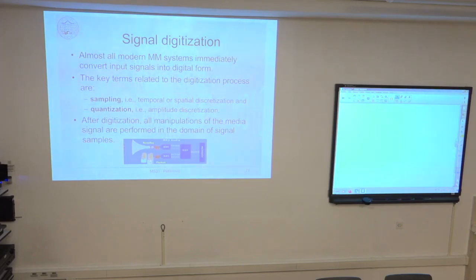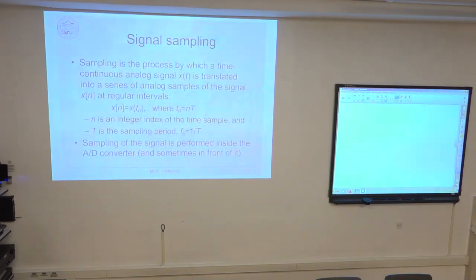For example, let's measure it with a multimeter, whatever, you have only a given number of digits to measure the voltage or the resistance, whatever. The same is with AD converter. It has a given number of quantization levels that is given by the design of this AD conversion. First of all, we will cover this aspect of signal sampling regarding time discretization.